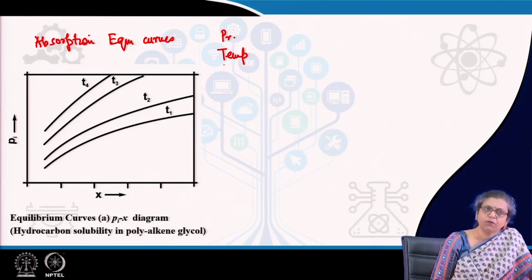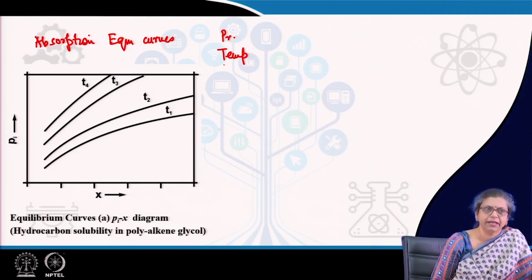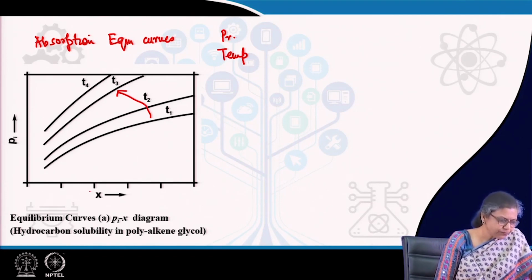So, for most of the absorption cases, they are accompanied by release of heat, or in other words they are exothermic. Therefore, for most of the cases we find that as we increase the temperature, the curve becomes more and more steeper and the solubility of the gas decreases.